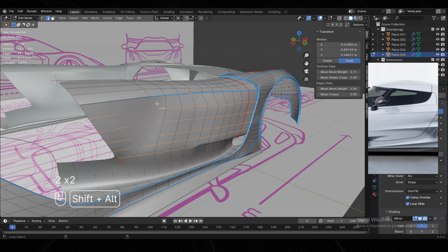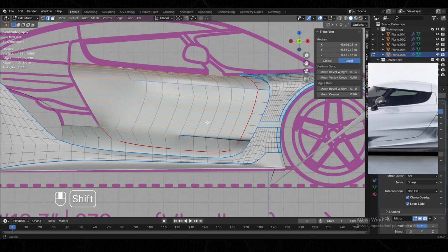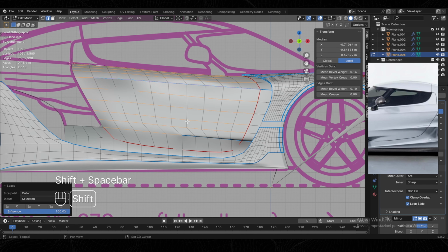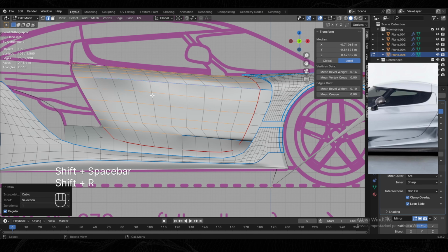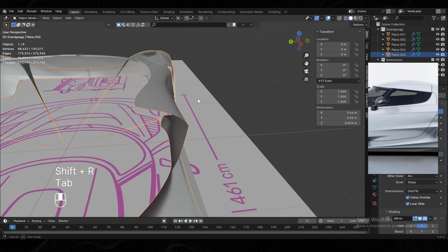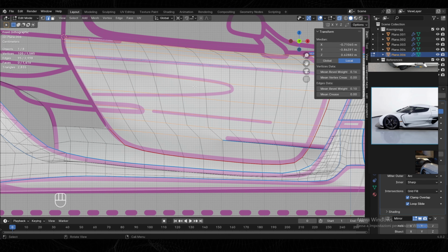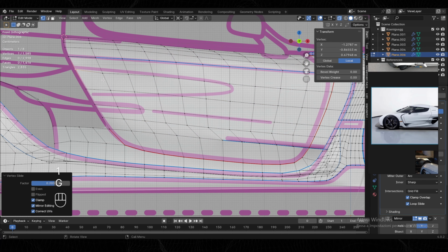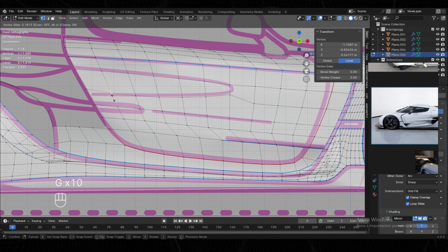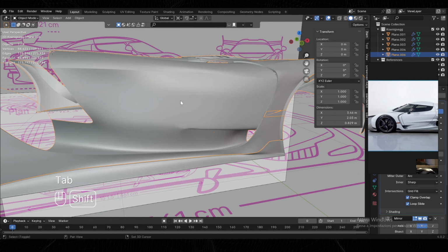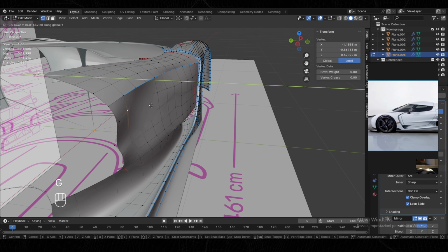And then space them correctly using your loop tools. Let's continue on by adding details now. I'm going to put vertices all around this line on my blueprint. Then I'm going to use all of this geometry to refine the car's shape.